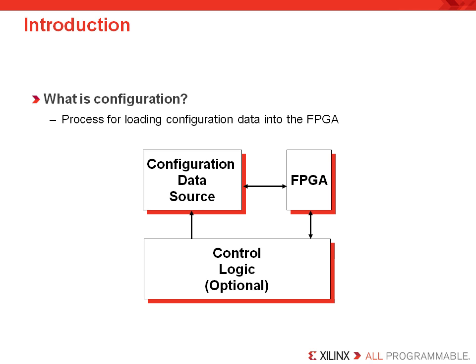multi-bit. Serial data paths are used to minimize the number of device pins required. Multi-bit data paths offered include by 8, by 16, and by 32 bit widths. These are used for higher performance or enable access to industry standard interfaces. These multi-bit solutions are ideal for connection to external data sources like processors or parallel flash memories.